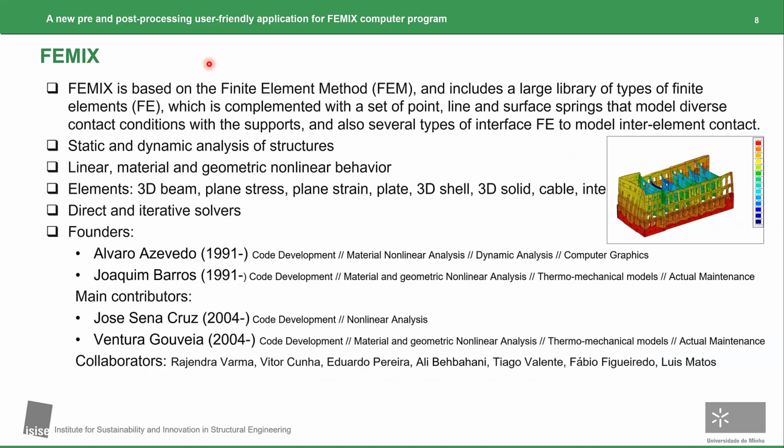And for processing, I'm going to introduce Femix, which is based on the finite element method and introduces a large library of types of finite elements, which is complemented with a set of points, lines, surfaces, a spring, and support different types of finite element models. It supports static and dynamic analysis of structures. Also, different types of linear and nonlinear material and geometric behavior could be performed by Femix.